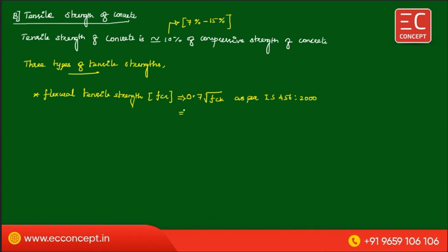Another is practically determined by using the 3-point load test. From this test we will obtain the flexural strength of the concrete.